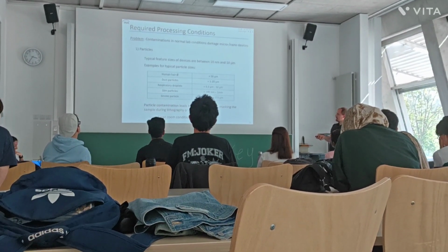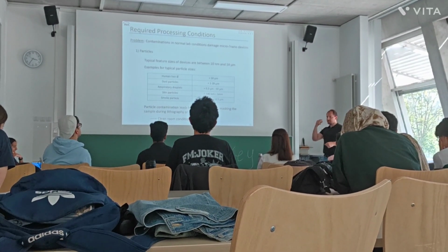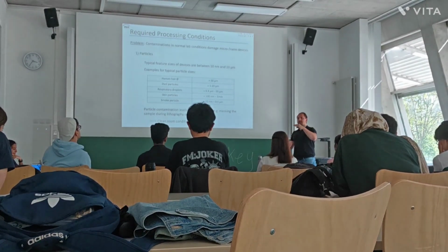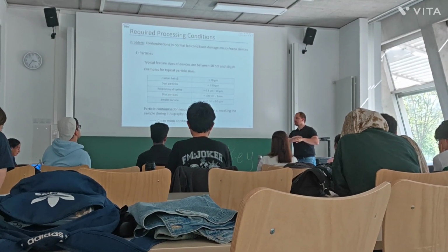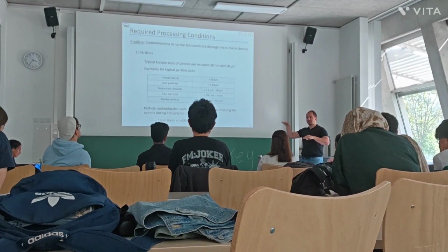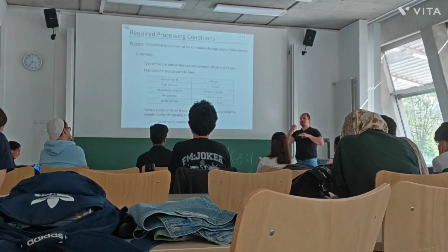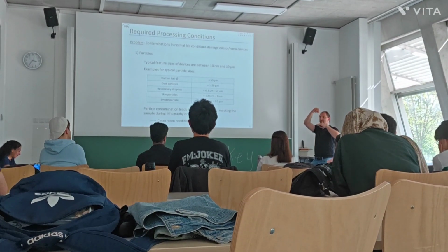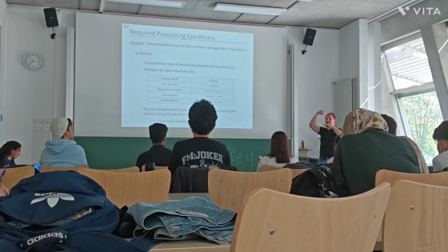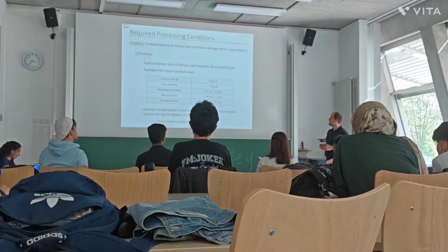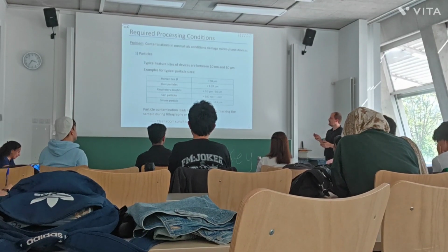This particle contamination leads to defects, and this is strongly happening in lithography, because you have to imagine what you showed already. We have a mask in lithography, so your particles act like this. You have a masking effect, so you transfer this particle onto your device. And this can lead to fatal defects, which we will see a little bit later.